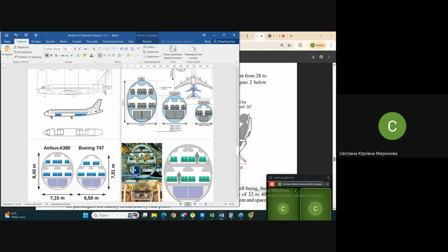Because during takeoff and landing, the airplane is not in horizontal position, and if this place is completely cylindrical, especially if the airplane has short landing gear, it may happen that during takeoff and landing, when the airplane increases angle of attack, the airplane breaks its aft on the airfield. It falls down by this place to the airfield. So be accurate with this.